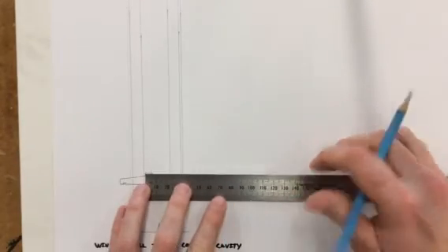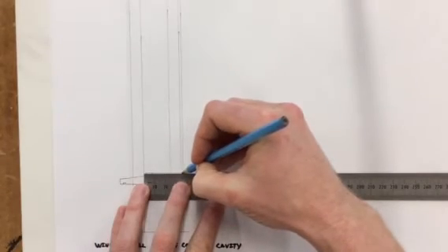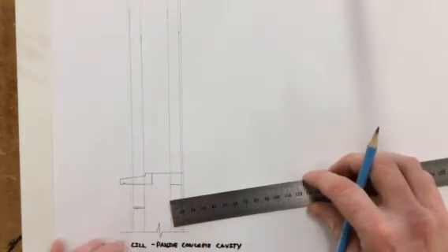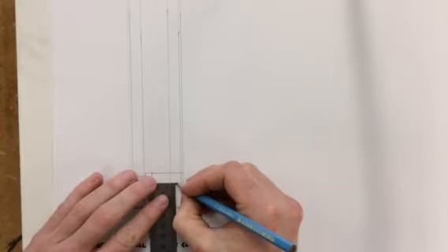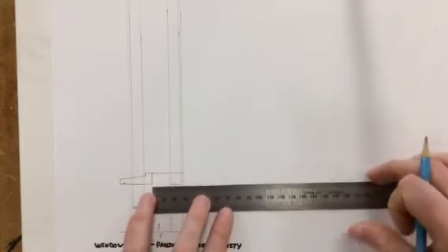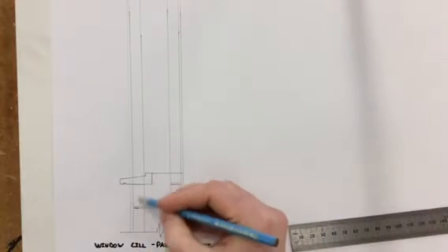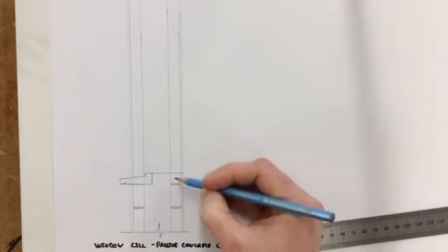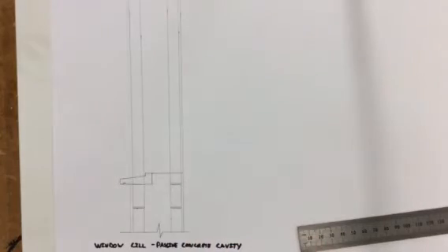So the top of that windowsill comes right the way into here. Right, so comes right the way across. Then you have one more small little block. It wouldn't be a full block put in there, but just to bring it up to the correct height. So you'd have 2 full blocks there, then 2 full, and then a half one.